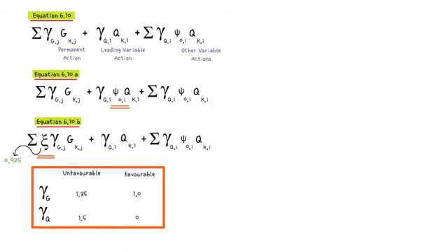There may be some situations where an action is favorable, such as an upwards load, which helps to stop the foundation failing. A permanent action has a partial factor of 1, since to make the design value of the action higher would not be conservative. A favorable variable action has a partial factor of 0, because it may not always be there.